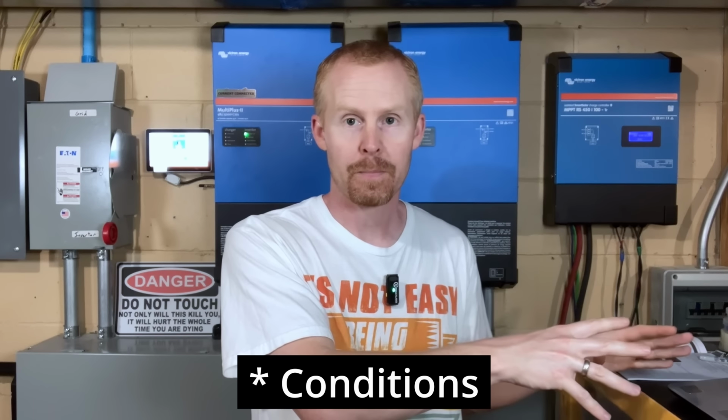And I discovered that I could utilize the relays off of the Cerbo to actually control when the AC input relays on the inverters were opened and closed. And that was using the generator start-stop ability on the Cerbo. There is a built-in generator start-stop assistant and virtual switch for the MultiPlus. But anytime you needed to make changes to those values, you have to get it back into the software. Whereas utilizing the Cerbo, that allows me to make changes from that touchscreen or from the VRM or from my mobile phone without having to get into any software at all.